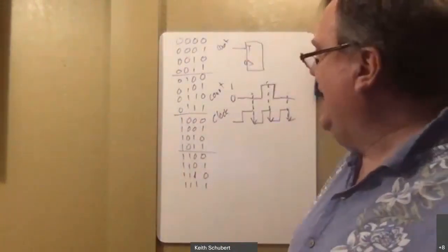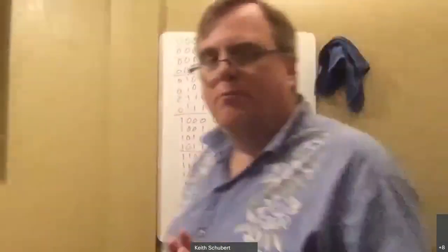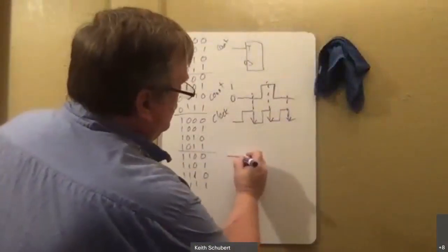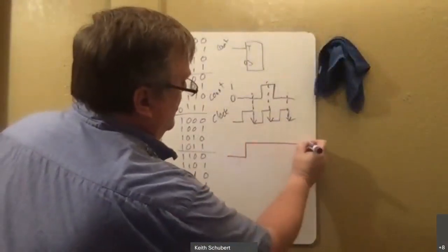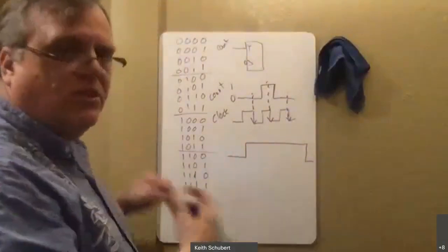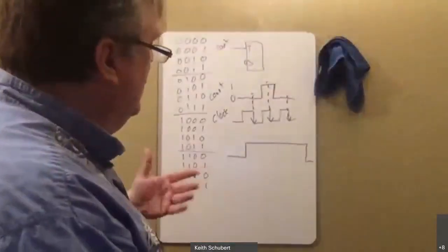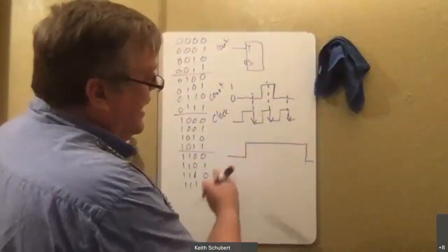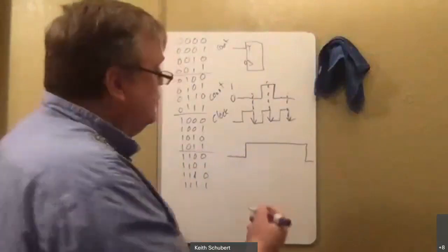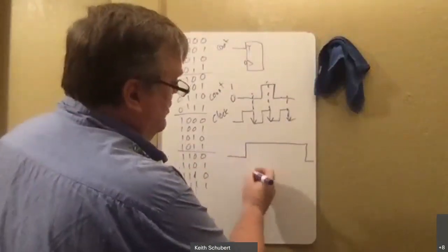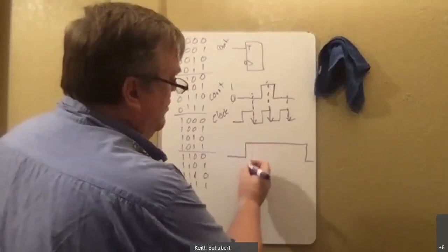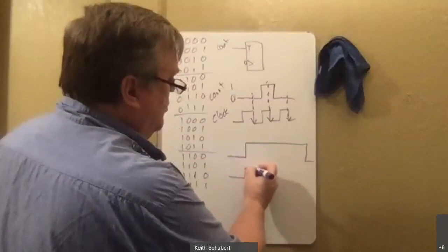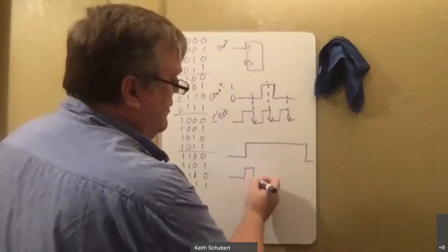Now, one way you can handle that, we won't build it here, but it's not a difficult one to imagine. Imagine I had a really slow-fingered person, or a slow-fingered system, maybe it's coming out of a system that has a much slower clock. If I only wanted to get 1 pulse out of this, I could do what's called an edge detector. So I can look for the pattern on the input that's a 0 to a 1. And whenever that happens, I want to cause a single pulse to go up during my clock.